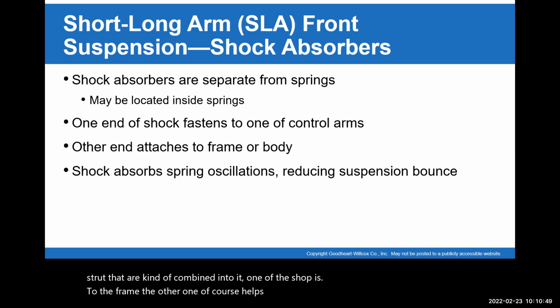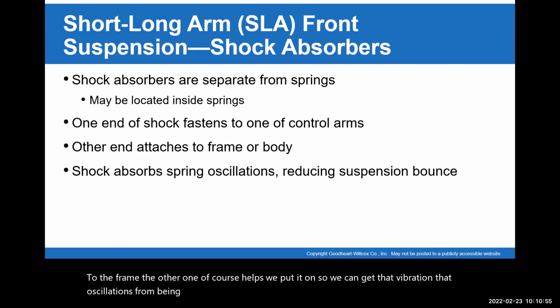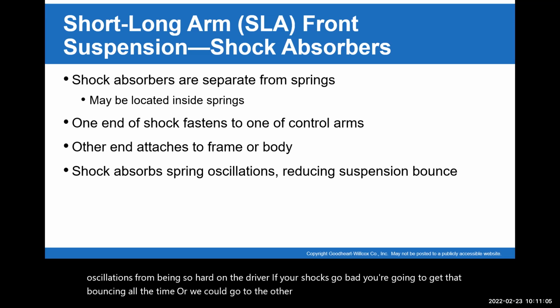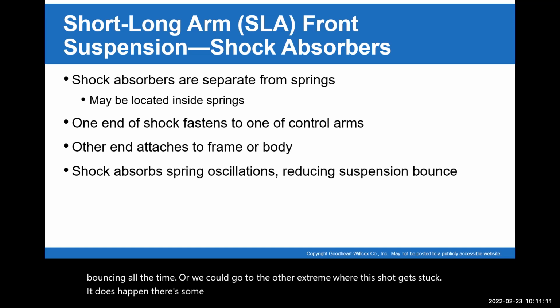We put it on so that the vibration and oscillations aren't so hard on the driver. If your shocks go bad, you're going to get that bouncing all the time. Or we could go to the other extreme where the shock gets stuck, and it does happen. There's some valving inside the shock absorber. We'll talk about that as we go along also.